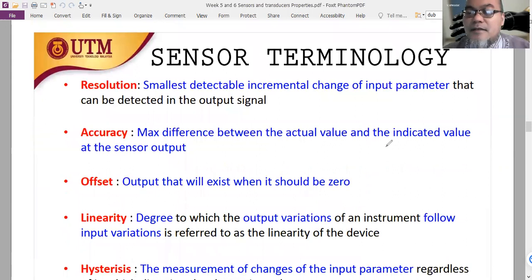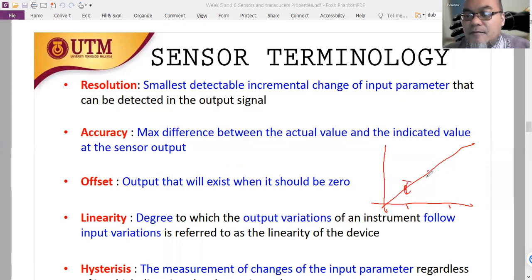So remember, yesterday, when we do calibration, this is obtained from several input standards. The more standards we use to do calibration, the better calibration chart we will get. And remember to also measure the background condition during the calibration, that is when you don't put any stimuli to the sensor.